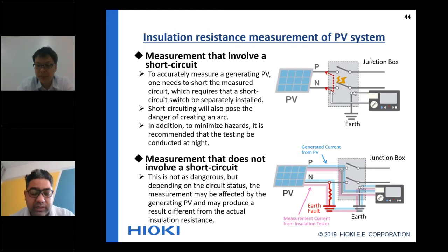So the insulation tester is a simple calculation, V = I R, right? The insulation tester applies the voltage, checks the current, and calculates the resistance. It is the same with all insulation testers. But especially in rainy time when the soil is wet, the current is different compared to the normal dry season. So Sagata-san tried to explain that the standard says we need to measure in that scenario. There are two conditions. We need to short positive and negative, and then we can do the measurement.